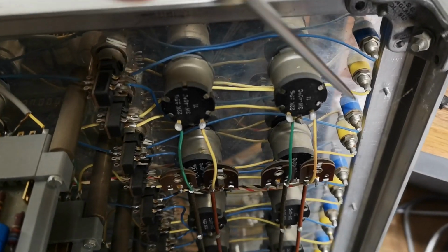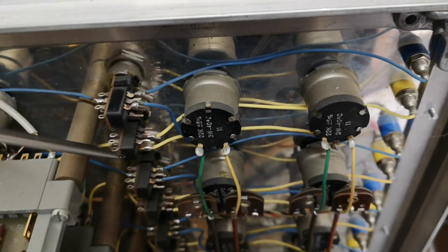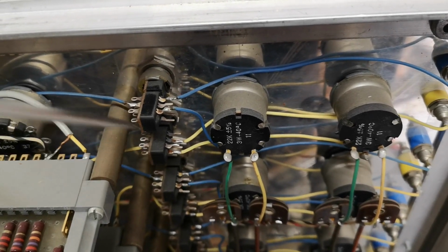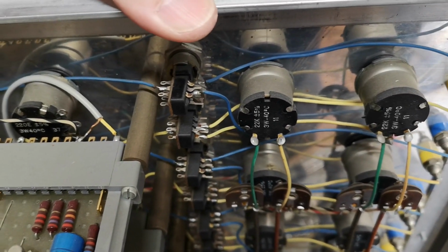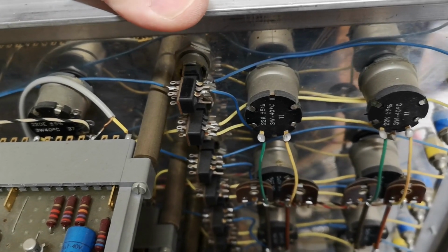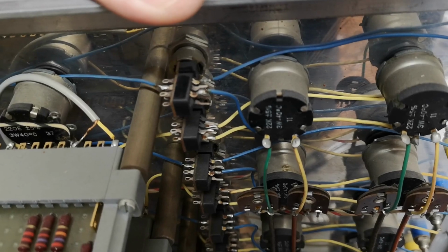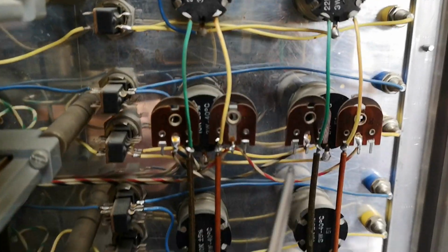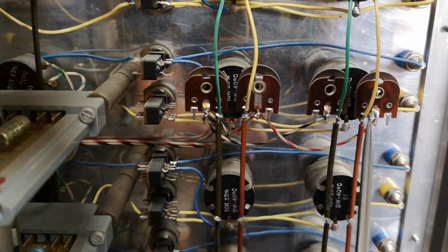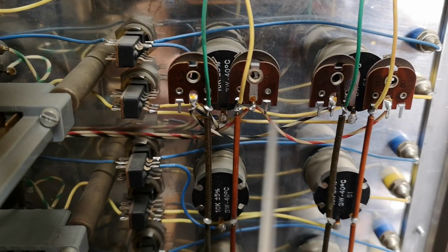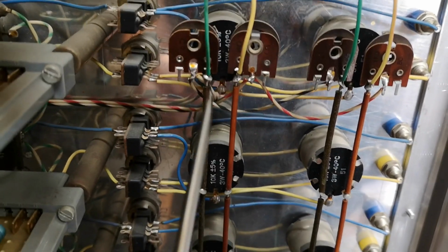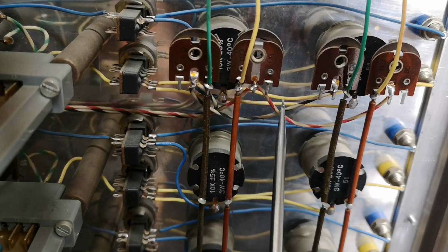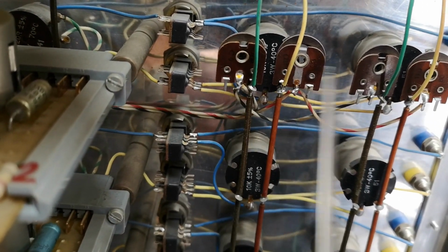We got positive and negative going signals for each of the generator features, and for some reason, you want to be able to manually override each of them individually by using 2 switches. I haven't yet figured out what is the purpose of that. Here we got like a global voltage setting using those resistors. I think this is the minimum and the maximum possible adjustment range you just set here, depending on the supply voltage, obviously. So that goes to those trimmers.